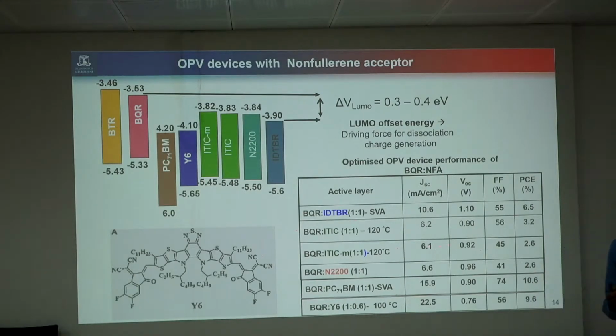When you want to generate efficient devices, with efficient manipulation of your exciton, we need to have a proper offset of donor and acceptor, and we need to have good mobility of the material so that charge can easily transport to the donor and acceptor phase and get separated out. Another thing is the built-in potential we are creating. The built-in potential we can manipulate with the interface between the donor and the metal we are using, and the acceptor and cathode layer. That's called interface engineering.